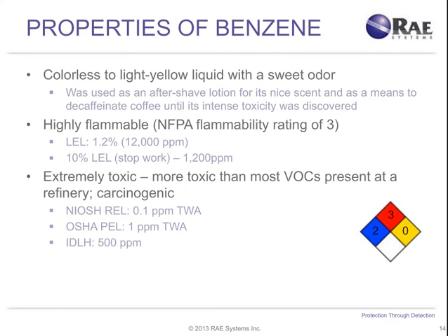Now, benzene is not only toxic, extremely toxic to be exact, it's also highly flammable. So at 1.2% volume, it reaches its lower explosive limit. Okay? So the stop work limit for benzene is 1200 ppm, 10% LEL.